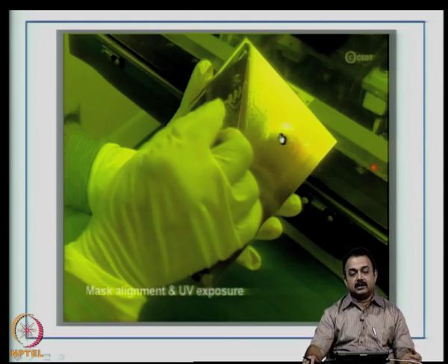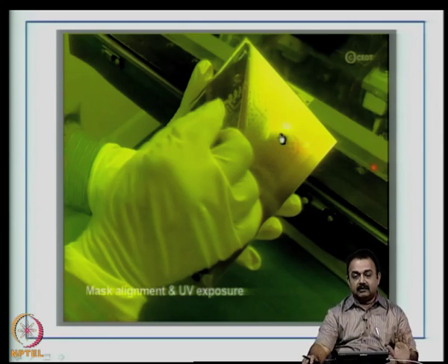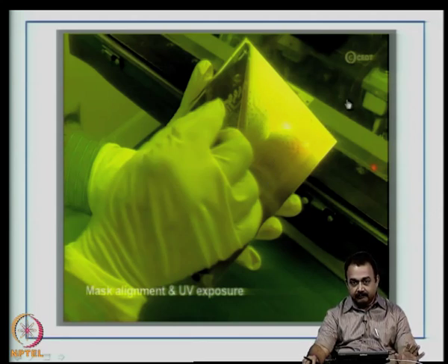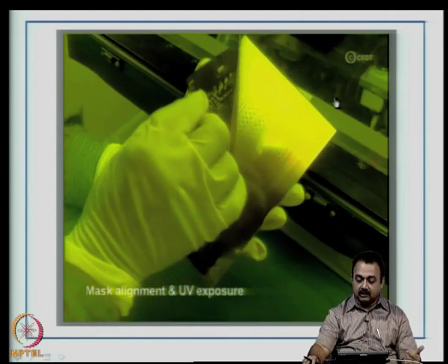So, here in this particular section the UV light intensity, the time for exposure, the thickness of the photoresist, cleanliness levels, the mask cleanliness, mask thickness, everything plays a great part in getting an excellent 1:1 translation if you desire. Now, you can imagine for PCB, if you are working with 4 mil lines or 2 mil lines, you have to have great control, quality control, and nevertheless for me to say that much more rigorous treatment you can expect in the semiconductor industry.